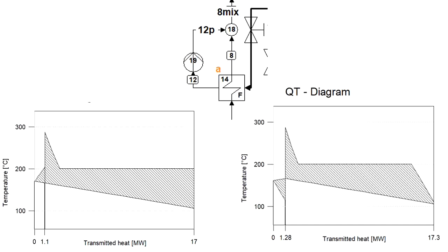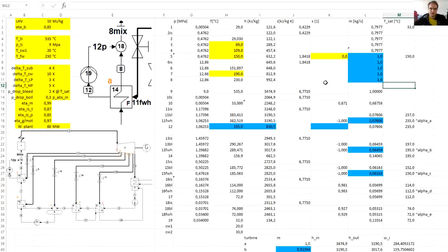Therefore, for the feedwater heaters with condensate pumping, we will assume the first possibility. The condensate outlet will be at the saturated level. Now we will implement our new configuration into the model. We will base the model on the previous one, just make necessary changes and modifications.